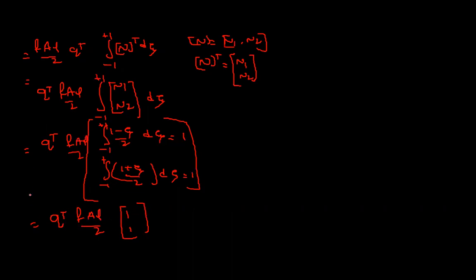So here this is called the entire body force term, but for a one dimensional member having a body force F, that is in Newton per meter cube. So therefore the body force matrix can be written as Q transpose into the body force for an element.